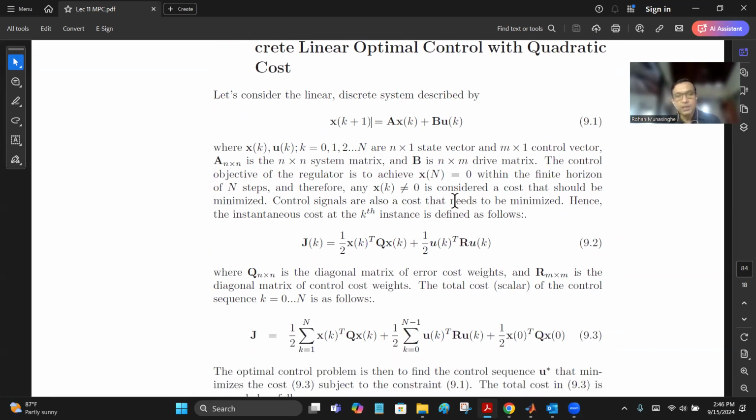So it says how state variables and control signals are linked or connected. It can be single input, single output. It can be multi-input, multi-output. So in some cases uk can be multi-input, more than one control signal going in, and xk is multiple state variables. The actual output is different to this one. These are state variables. The actual output can be one or many of the state variables.